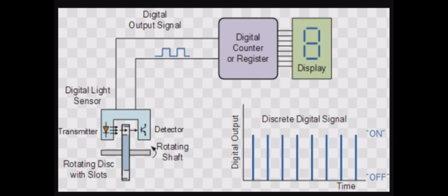And the major benefit is it can operate on both AC and DC as well. As each and every device has its pros and cons, the PLC also has some cons. The disadvantage of the relay output is that it is used for slow switching applications because the relay takes time to energize the coil.